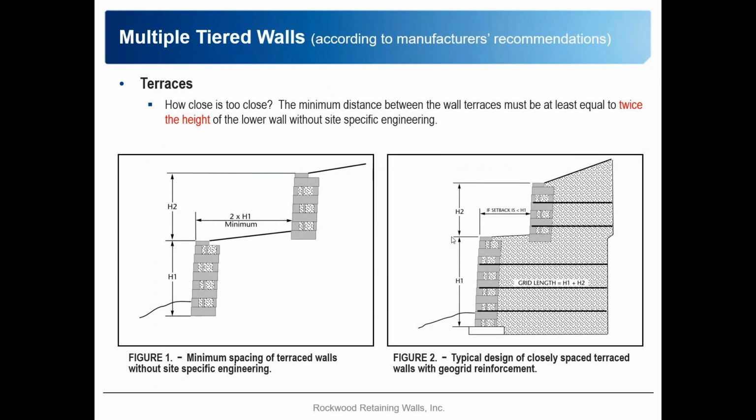Tiered walls. Our recommendations from Rockwood are, if you look at the overall design height from the top of the leveling pad to the top of the cap, you should maintain 2 feet, 2 times that height.